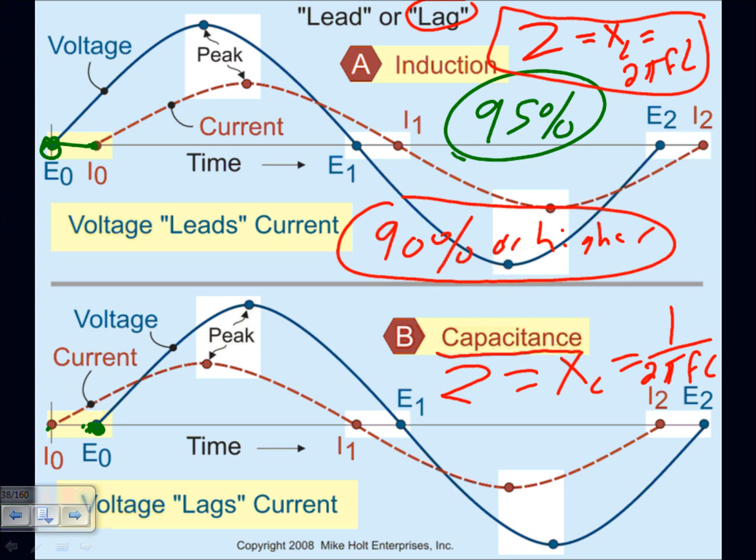I always look from left to right, from this side. The first thing you hit is what? The voltage. Voltage leads. So if the voltage leads, what happened to the current? Lags. Remember, Chad gets into looking from right to left sometimes, but I don't think you have this issue though. Any questions, guys, about this? I promise you we're going to be correcting power factor for commercial buildings and so forth as we go through.